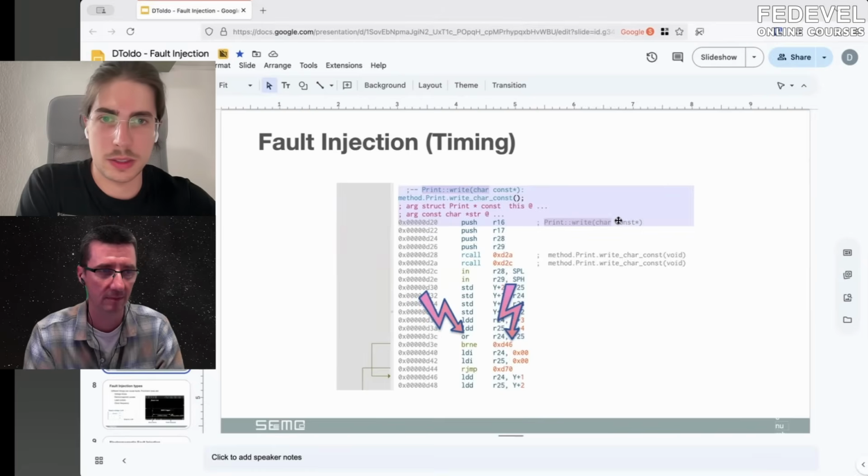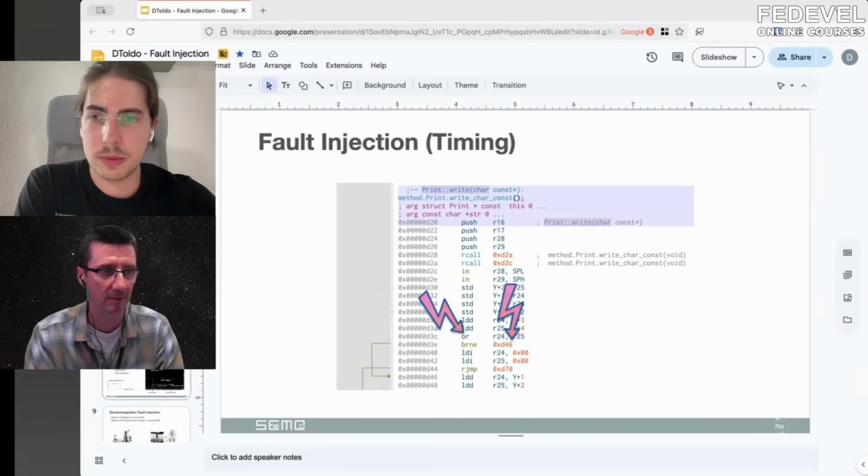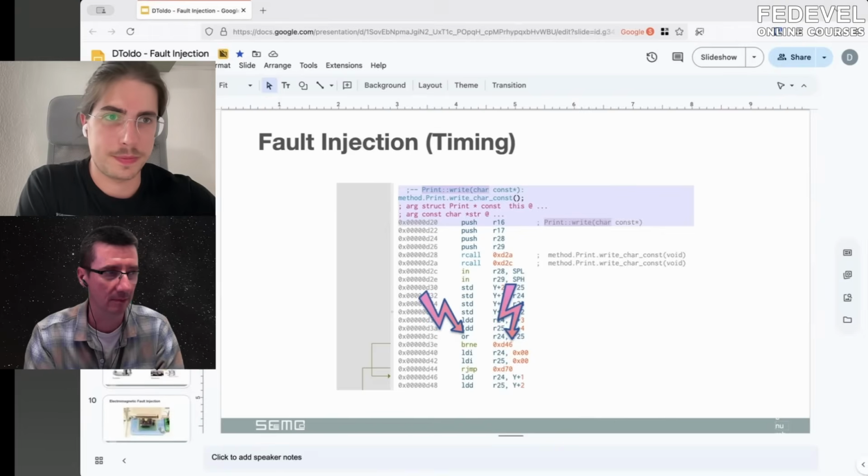Yeah. But what I want to show here is that even looking at your firmware through a decompiler, in this case I use Ghidra, which is open source, you can look at your firmware and see if these checks and important code parts are gone, or if not. Because if they are still in your firmware, somebody could jump to it. So it's something good to do if you have critical stuff in your code.